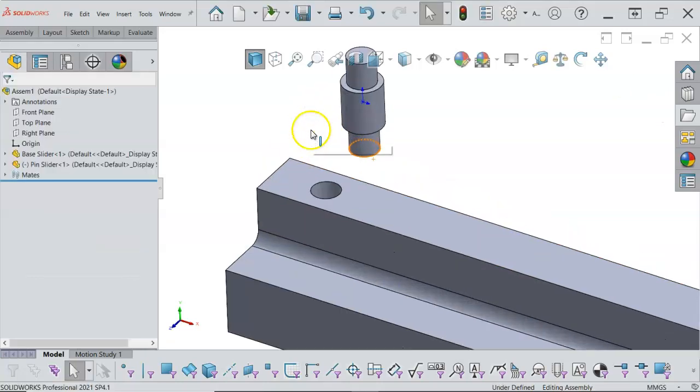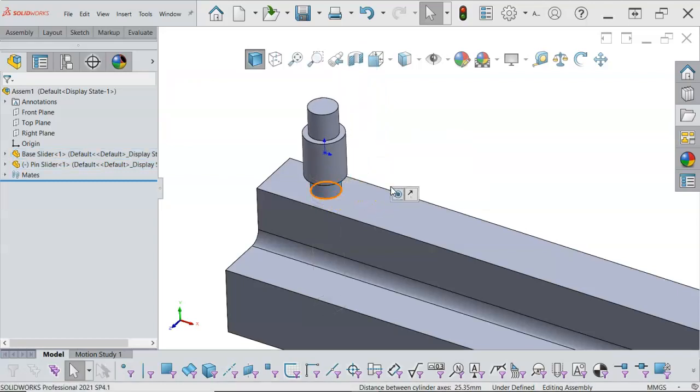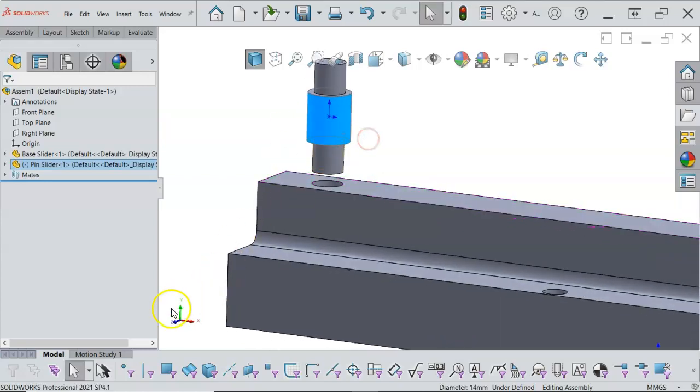So I'm just going to place it and then select and control select. All right, so selecting the cylindrical face, going to the mating cylindrical face and making it concentric. Don't move the mouse, wait for a good 2 count, and then we can lock the rotation. So once that highlights, now this is going to keep it, it'll move up and down, our 6 degrees of freedom again. I'm now able to move in Z, but not rotate about Z, or in this case, Y.